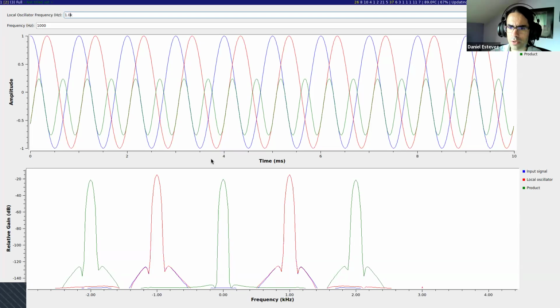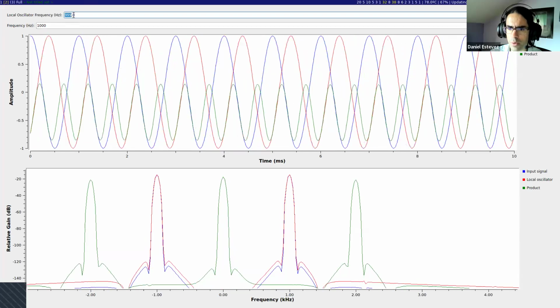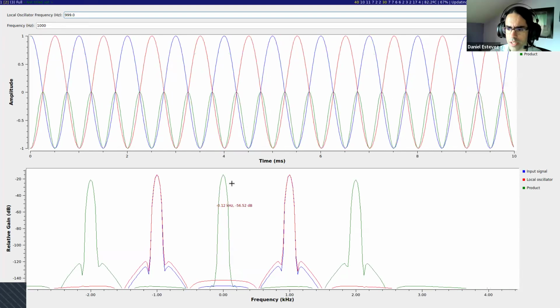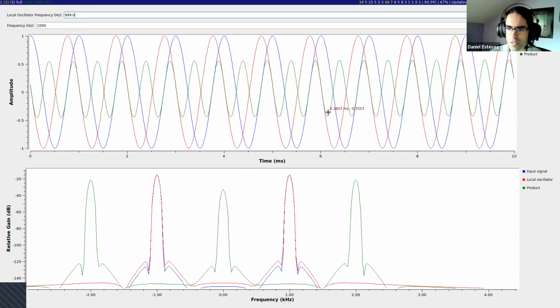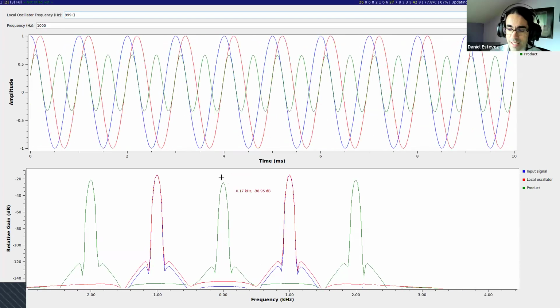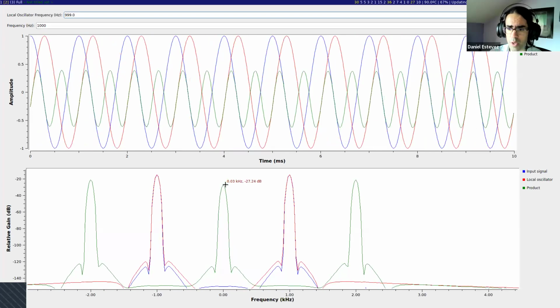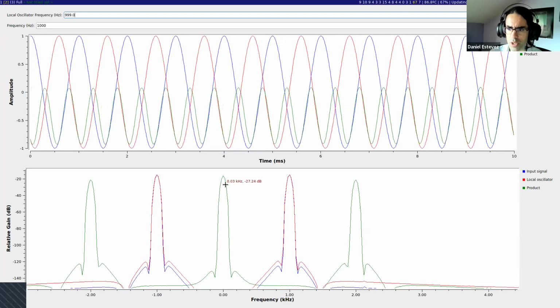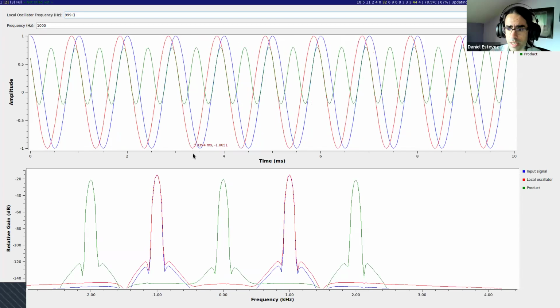Yeah, the example about two signals which are slightly of a different frequency, that is a good one. We can simulate it here, for example, by setting a difference of 1 hertz. And you can see there is this whoa, whoa, whoa effect, which is basically a 1 hertz tone that we can see here, not very well because of the FFT resolution. And that comes up in music all the time when you have two instruments which are slightly out of pitch. You can hear this beat frequency, which is how it's called.